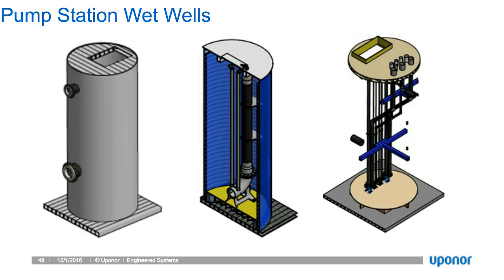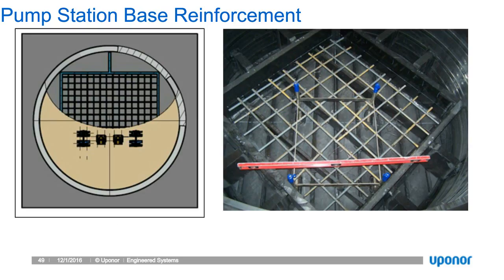One thing to note with our pump stations, it's an important thing that comes up, and we get the question from time to time, as you would expect, if I have extremely large, high horsepower pumps that are anchored into polyethylene, that are rocking on and off and have vibratory loads, we want to counteract those vibratory loads and that thrust of the pump with a concrete base.